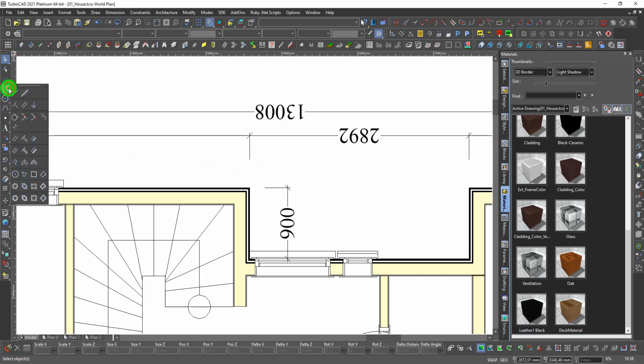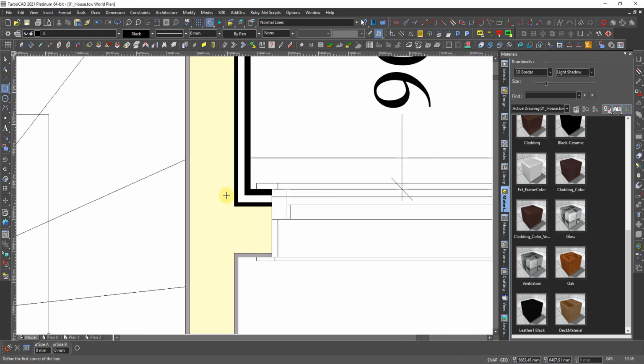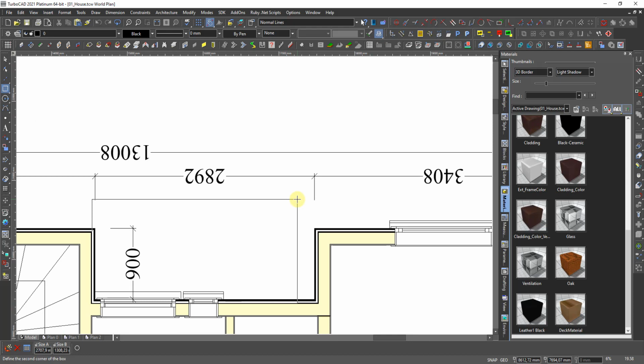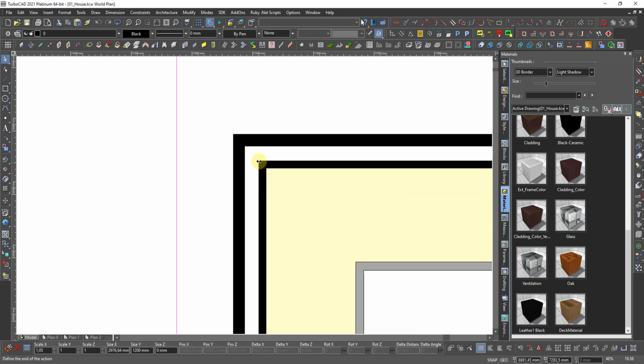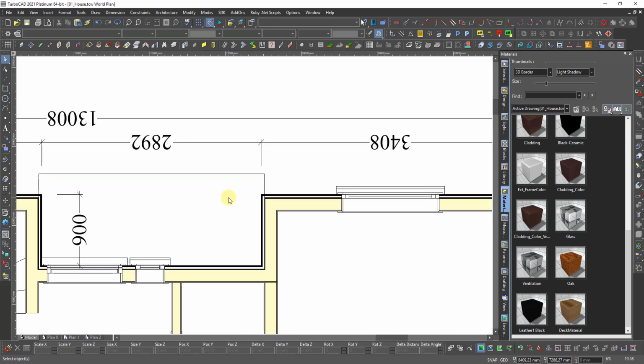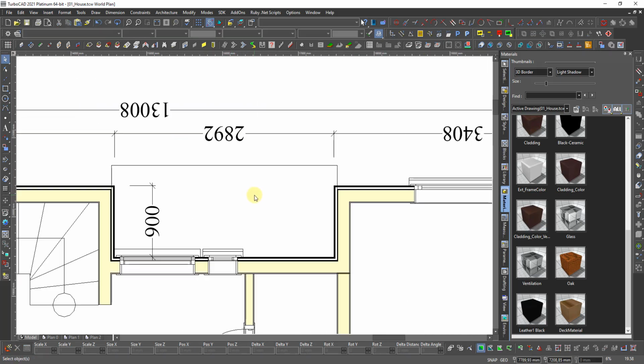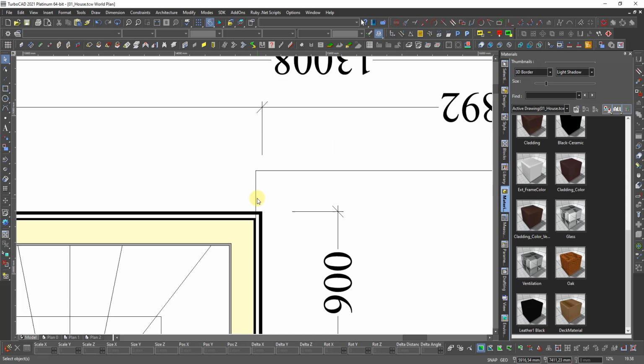So I draw a rectangle from, it must be from here then, on V, and then it should be 1200, and I take this and I drag it to V. That's this one, and because this is an outdoor stair, we like to use 300. So I offset this. No, not this one. Not yet. I will drag this.